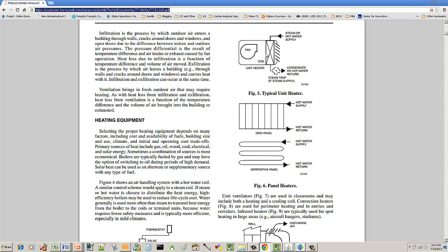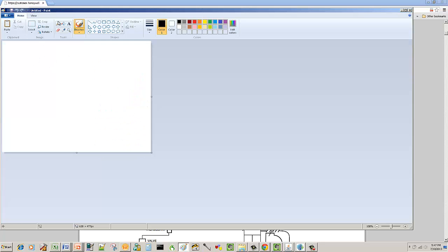And the thing with heat, whenever you see a VAV box that's heating, let me see if I can draw a little picture here. Alright, so right here we've got a VAV box. There we go, there's our box. We've got airflow coming through, and here's our damper, and maybe here's our heating coil. Let's just call that a coil. I know it looks more like an averaging sensor. Okay, now it looks more like a coil. Our damper's right here, the airflow is coming through, and our damper throttles the airflow.